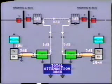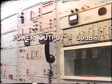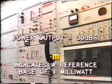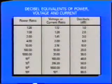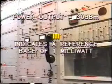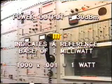An advantage of the logarithmic figure is that the dB values can be added arithmetically in order to find the total dB loss. You will often see a reference to power output in terms of dBm, say 30 dBm. The M indicates a reference base of 1 milliwatt. To find out the actual power, we need to multiply 1 milliwatt by the original power ratio. From our chart, we see that for 30 dB, the corresponding power ratio is 1,000. So the 30 dBm power indication is equal to 1,000 times 0.001 equals 1 watt.